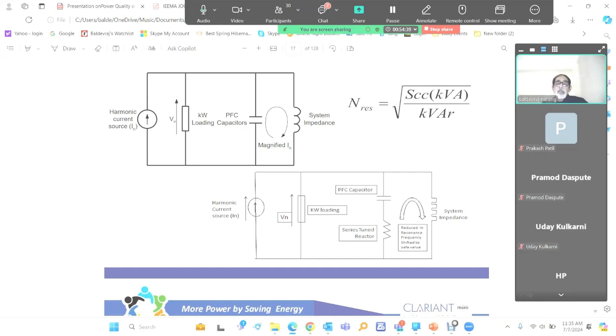Nobody uses them. And when we are connecting capacitors with a reactor like this, there is a voltage rise across the capacitor. Suppose there is a 7% reactor, the voltage will increase across the capacitor by 7%. And suppose there is a 10% tolerance also. So what we do is, for a 440 volt system, we use 525 volt design capacitors, otherwise they will fail. So this is how we control the harmonics in the power factor control system itself.